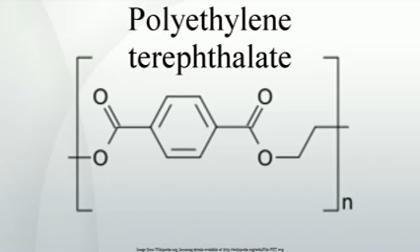Special feature are, acetaldehyde and oligomers are contained in the pellets at lower level. The viscosity is reduced somehow, the pellets are amorphous and have to be crystallized and dried before further processing. Processing to a PET film for thermoforming, addition to PET virgin production, BOPET packaging film, PET bottle resin by SSP,